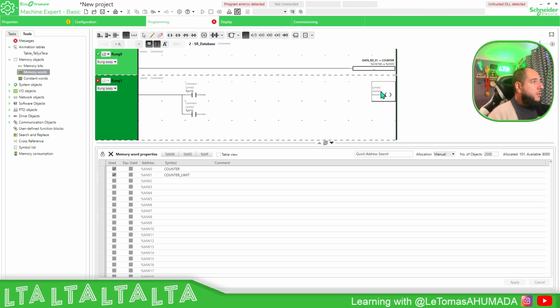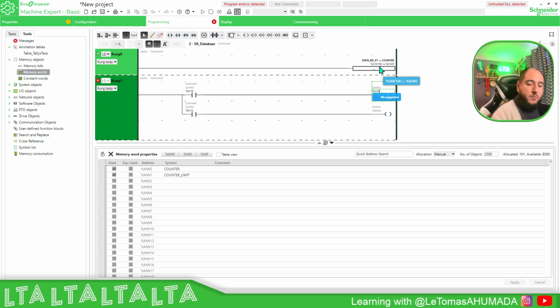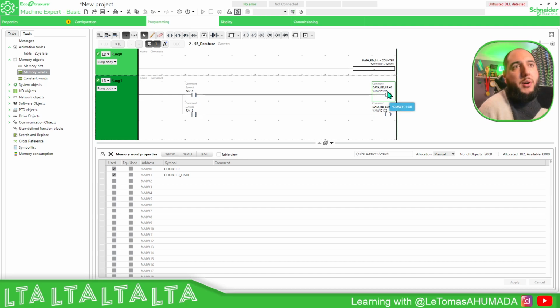You can link them directly into MW100, then colon X and the bit that you want, and MW101:X2. This one's going to be 101. So here you prepare the information for the other system to read. Nothing special so far. The other devices need to read the MW100 standard.